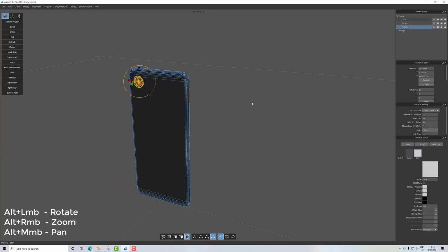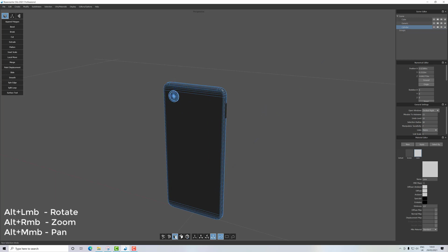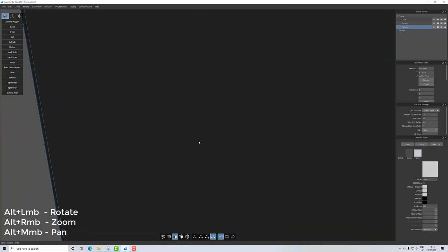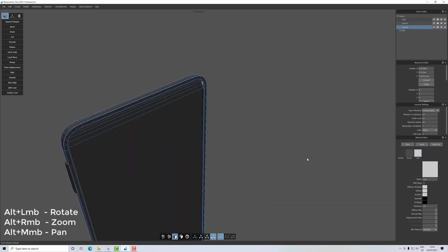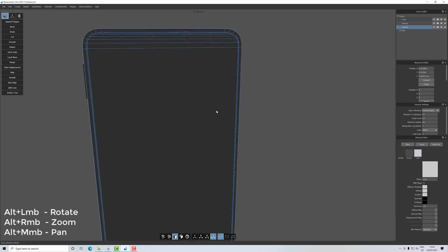So if I select the cylinder, which is our camera, I can use my select there. I've got the kind of draw select mode on, and just select all of those pieces in the middle, and then on the material editor I'll select lens and then apply.